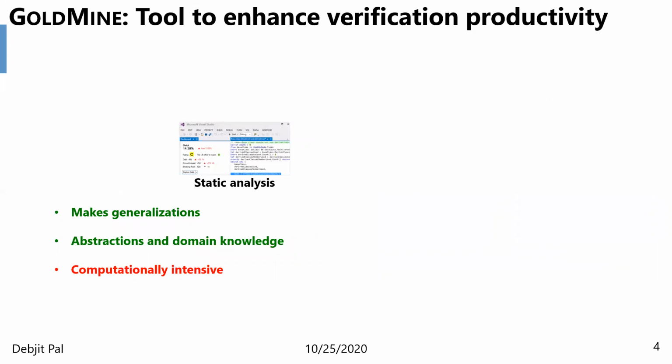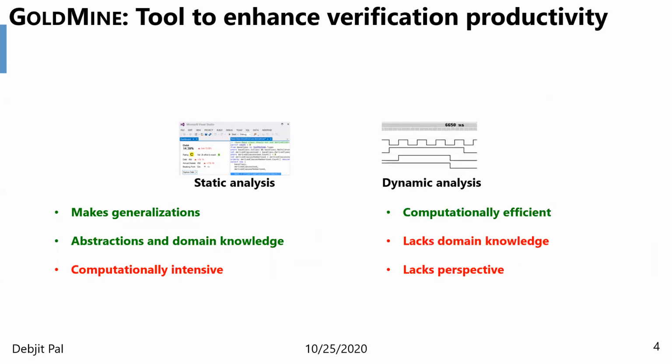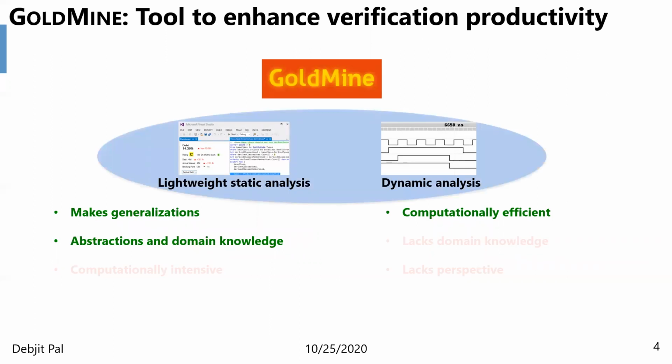Static analysis-based methods analyze design source codes without actually executing the design. Static analysis can make excellent generalization, but is computationally intensive. On the other hand, data-driven dynamic analysis-based techniques, such as machine learning methods, are computationally efficient, but lack domain knowledge and perspective. In GOLDMINE, we inherit the best of both worlds. We perform lightweight static analysis of design source code to gather necessary design domain knowledge such that the machine learning techniques can be guided with adequate perspective to perform a plethora of verification tasks.